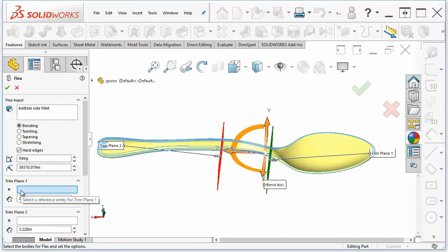And the fact that there's no selection here just means that you haven't created a parametric selection, such as a sketch point or a hard model point to place that plane.